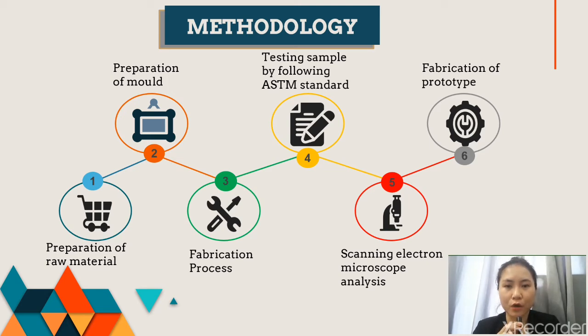The working principle of the guarded hot plate is, first, the sample is placed between two plates. One plate is heated and the other plate is cooled. The temperature of the plates is monitored using thermocouples until they are constant.